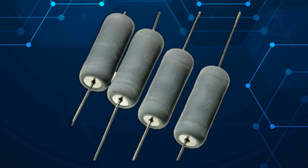Semiconductor devices: components like transistors and diodes have power ratings that specify the maximum amount of power they can handle while maintaining their electrical characteristics. Exceeding this rating can lead to semiconductor device failure. Transformers: power transformers are rated based on their capacity to handle both voltage and current without saturating or overheating. Transformer power ratings are commonly expressed in volt-amperes, VA.